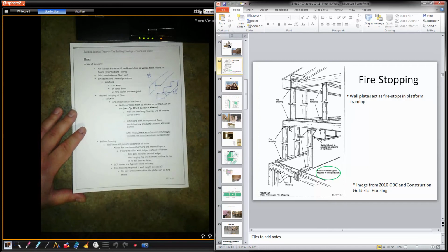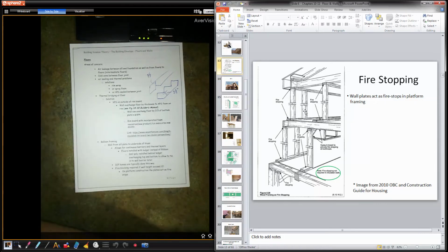It also helps with strengthening the wall. So if I had a stud from here to here, balloon framing, and I put a load of blocking in there, it stops the fire from traveling through, but also gives the wall more integrity. So it won't fall apart, and it takes longer to burn through, so less likely for the stud to collapse and the building to collapse.